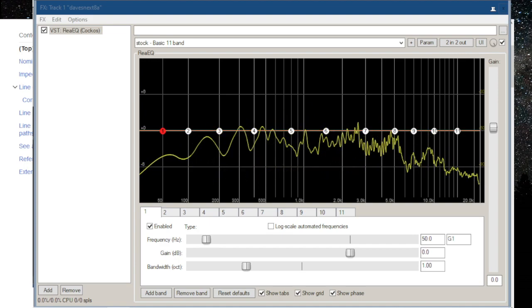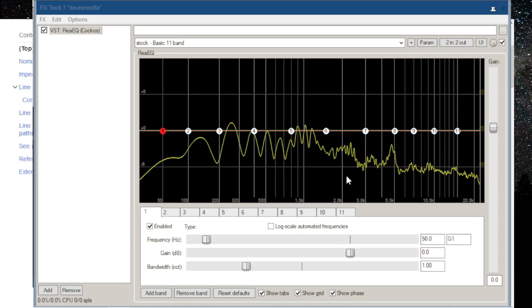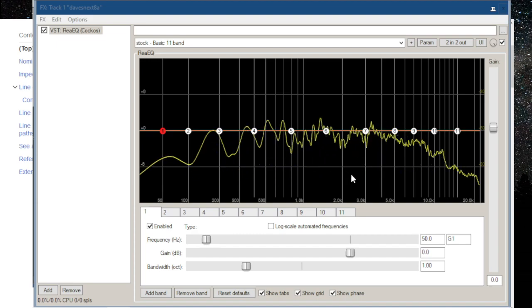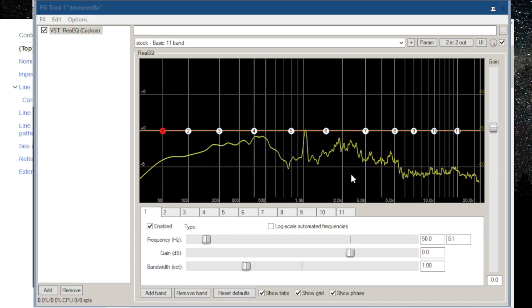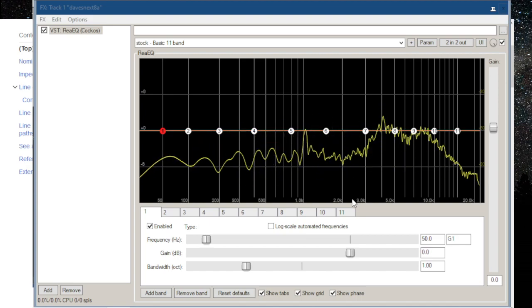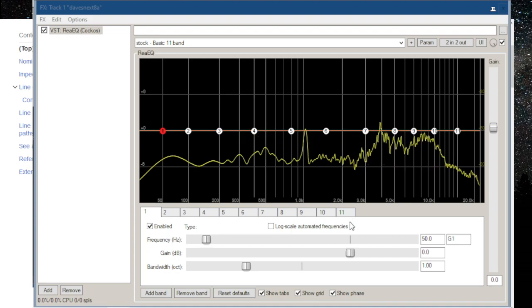So now the only situation is those two harmonics. They're showing up in both generators, which tells me the harmonics are coming from somewhere outside of the input source.